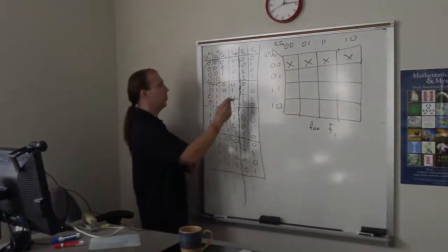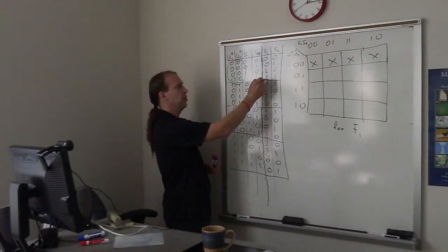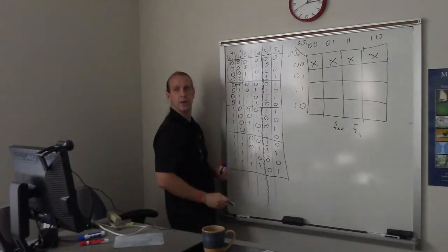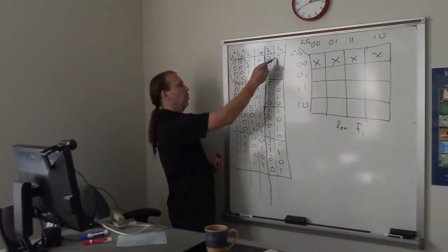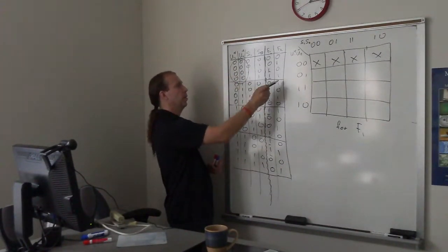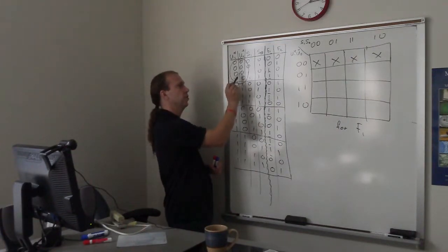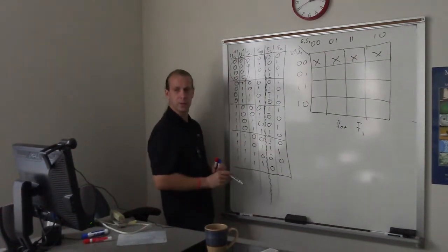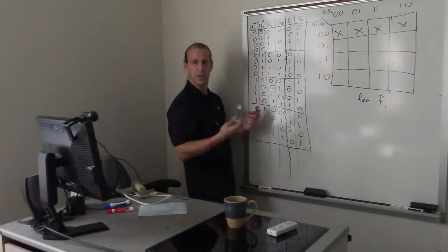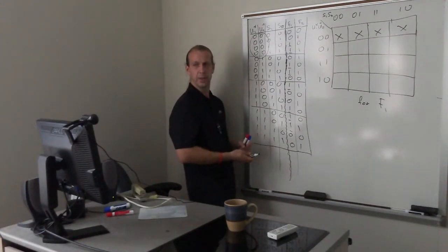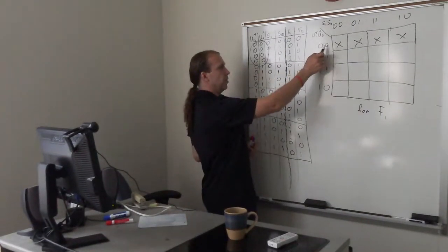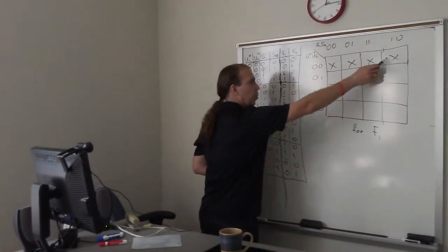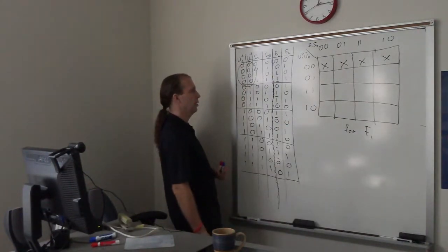It doesn't matter that we have ones in here, here, here, and here. It is good for us that any row in this table with the combination 0, 0 is a don't care condition. We know that this is no operation. It should not affect the state of the finite state machine. That's why we put 0, 0.